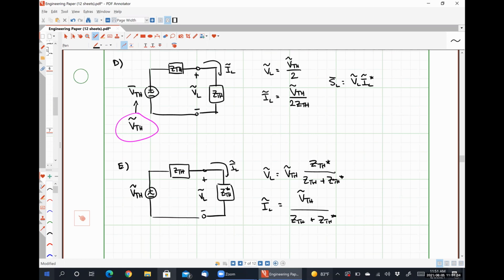So a very common mistake, and I don't even really want to call it a mistake, but a thing that students seem to miss when they're doing these homework sets: if you're calculating anything that you will use complex power to get, you need to make sure that you're using the RMS values. You can tell whether you were given the RMS values of voltage and current if the units are expressed as volts RMS and amps RMS.